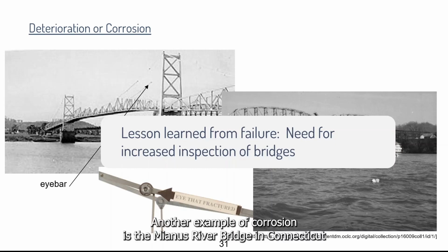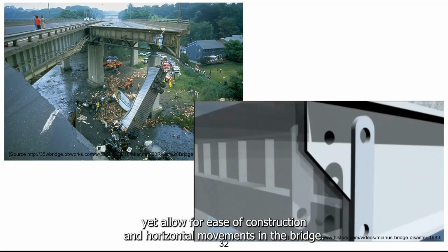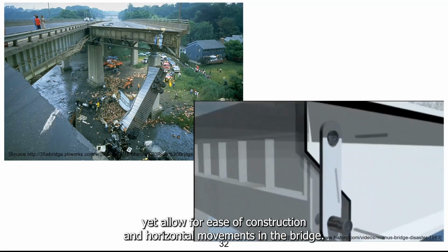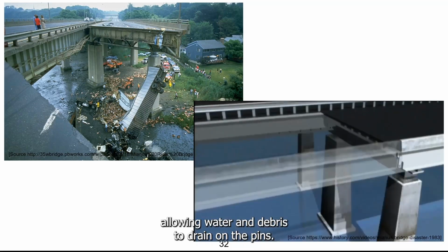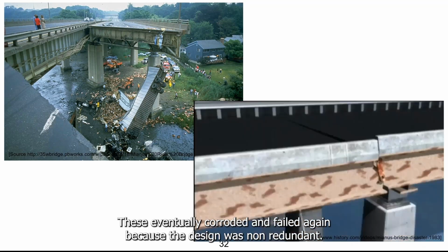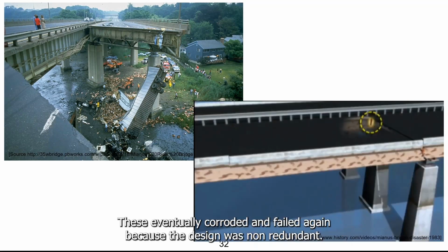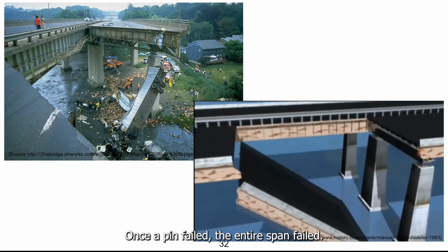Another example of corrosion is the Mianus River Bridge in Connecticut that collapsed in 1983. The design used a pin and hanger assembly to support the spans yet allow for ease of construction and horizontal movements in the bridge. The drains on the bridge were plugged, allowing water and debris to drain on the pins. These eventually corroded and failed. Again, because the design was non-redundant, once a pin failed, the entire span failed.